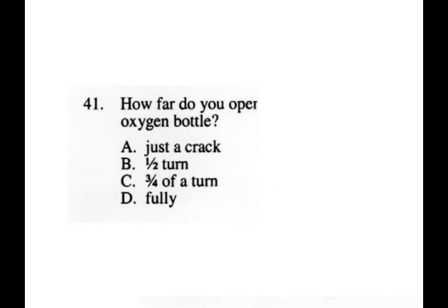Number 41. How far do you open the valve of an oxygen bottle? Just a crack, half turn, 3/4 of a turn, or fully? The answer is letter D, fully. Reason for that? It's a double-seated valve, and without fully opening the valve, there's risk of leakage.